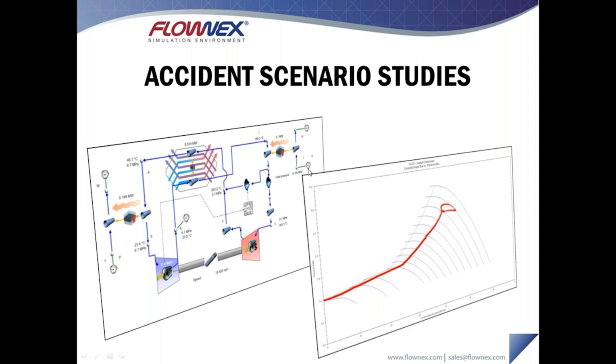So the scenario that we're simulating is a loss of heat on our heat source. In this scenario, what we want to do is first decouple our turbine train from the generator. So this turbine train with the shaft is set to run at a constant speed. We then disable that and let the shaft calculate its speed based on the power balance between these two components.